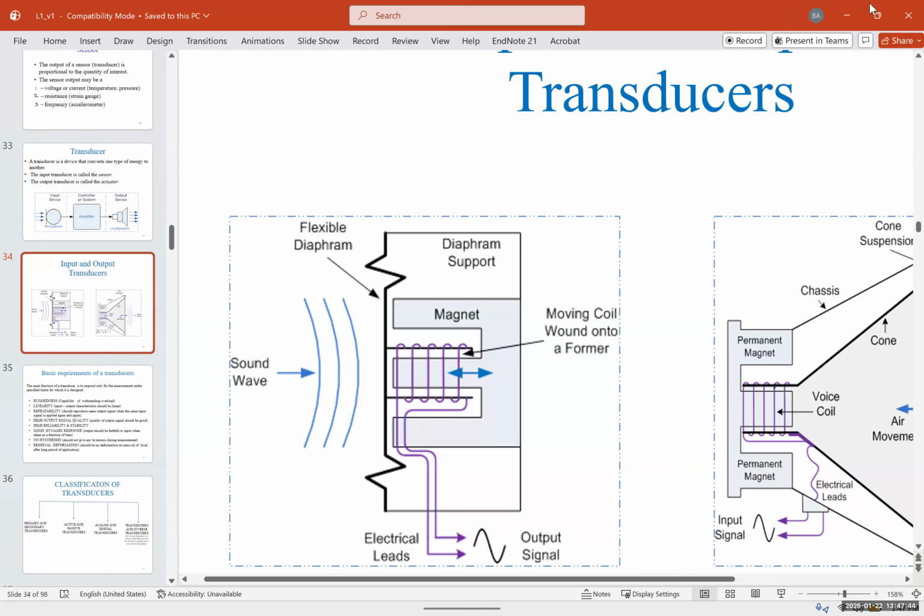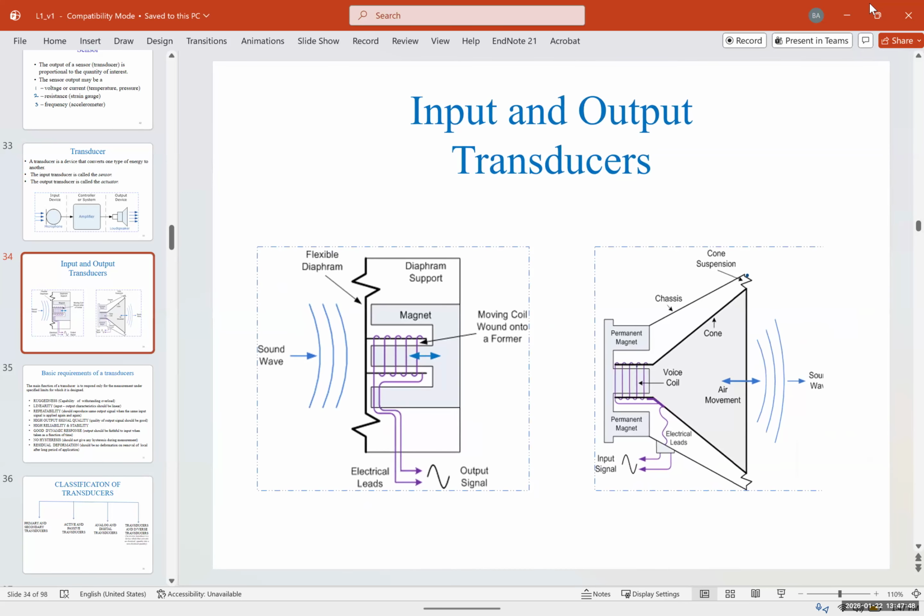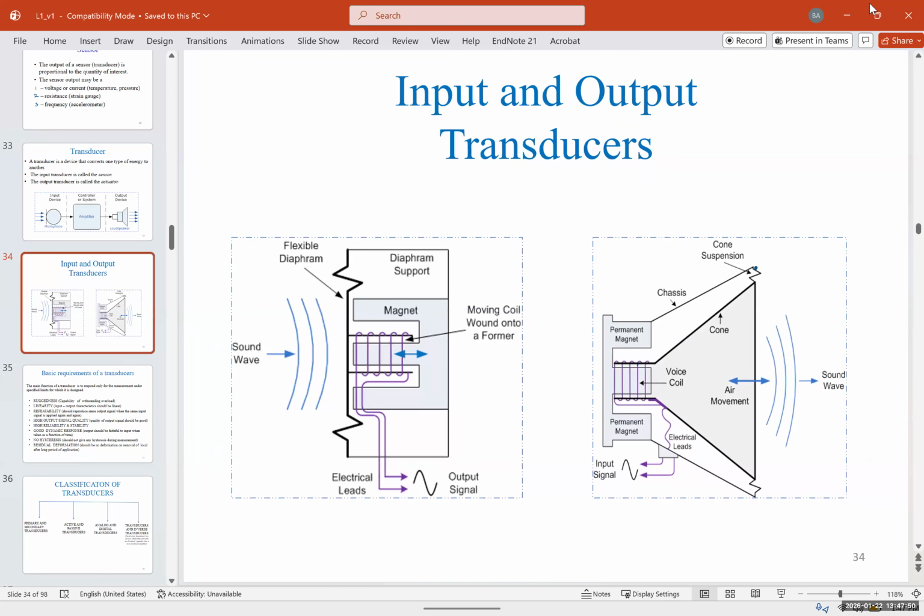Do you have any questions from this? Why do some microphones require power to get through? Those are active microphones. Again, they are using that to amplify the signal, so you're going to have an amplified signal. And it's best to amplify the signal at the source. Those are better ones because when you do that, you have a better signal to noise ratio.